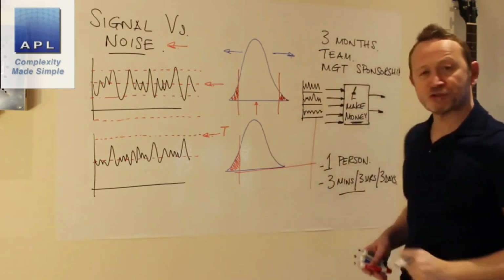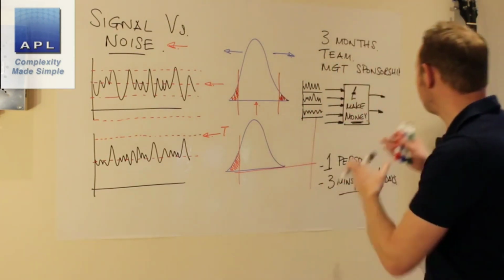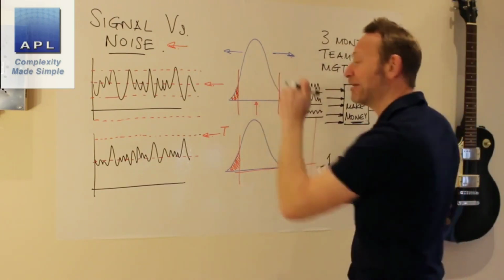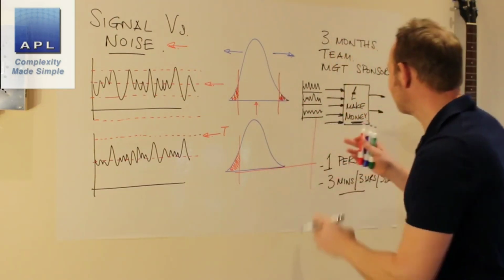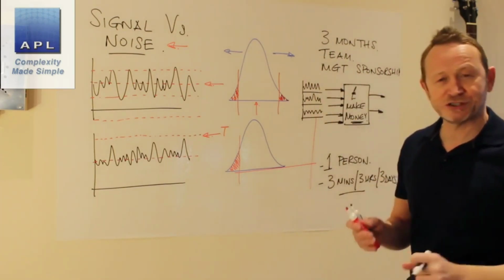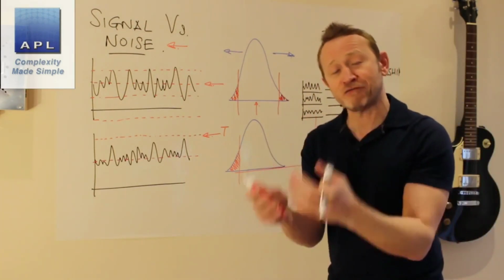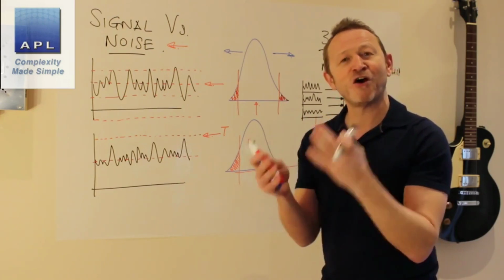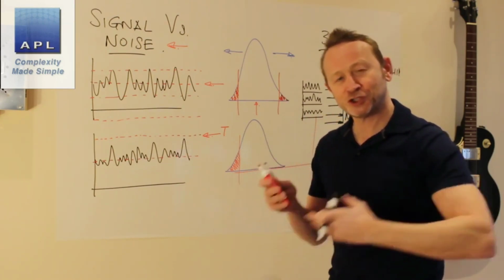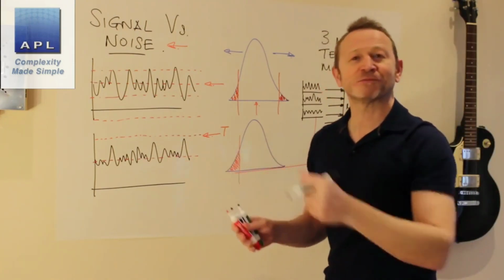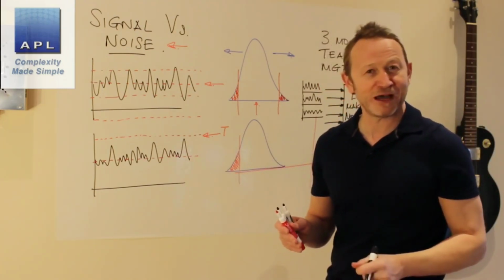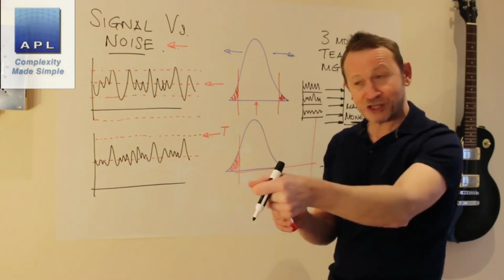And when you have too much variability coming in, you are going to get too much variability coming out, and you are going to get a problem with noise. Now, as I say, these are often deep-seated. They may be that you haven't provided the maintenance on your equipment, so the machine is behaving badly, and then the operator is trying to buy that bad behavior off by adjusting settings.